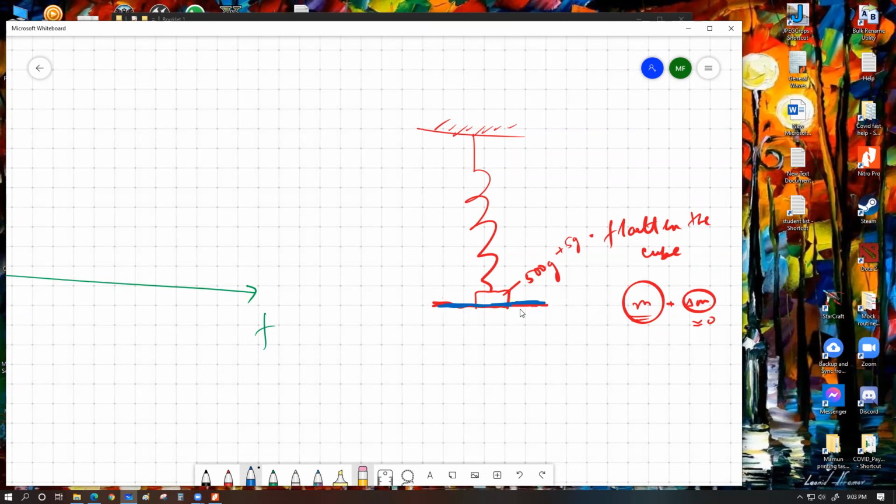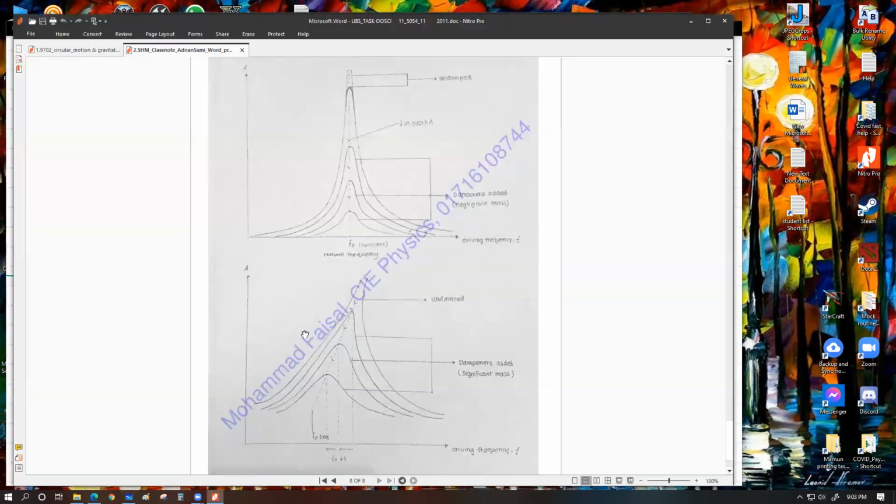This will also increase the air resistance significantly, but because this is another metal piece, it is possible that the increase of mass might be significant. If we have a significant mass increase, then the natural frequency of this whole oscillating system is going to be lowered, because a more massive object will tend to move slowly. And that is what is shown in this second graph over here.